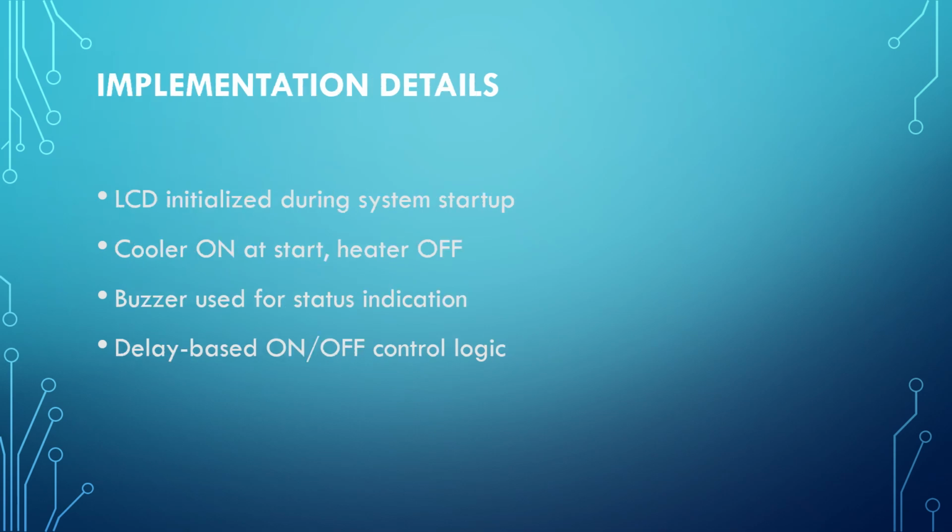Coming to the implementation of the system. When the system is powered on, the microcontroller first initializes the LCD and displays the system status. This helps the user immediately understand the system is active and working. In this initial stage, the cooler is enabled and the heater remains off.